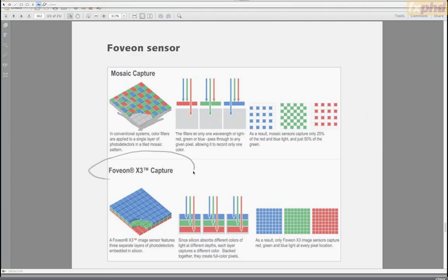But I want to mention in passing the Foveon chip, which you might have heard of, has a process of separating colors through the absorption depth of the photons in the silicon. So basically, photons get converted to electrons in the top micrometer or so of the silicon. And the Foveon guys made this very sophisticated chip that pulled them out into 3 separate signals, and they didn't have to do mosaicing. They didn't have to do demosaicing.